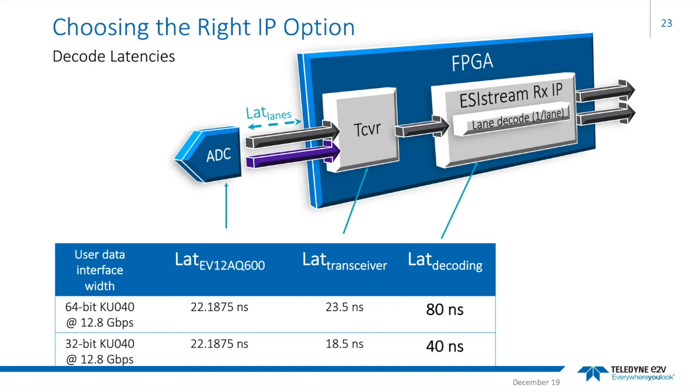I just want to take a quick look at the various system level latencies that a designer will have to consider. In this example, the latencies identified have 4 separate sources. There's the latency through the ADC, it's fixed, and that's around 22 nanoseconds here. There will be a finite latency as the data travels through the serial link to the FPGA.